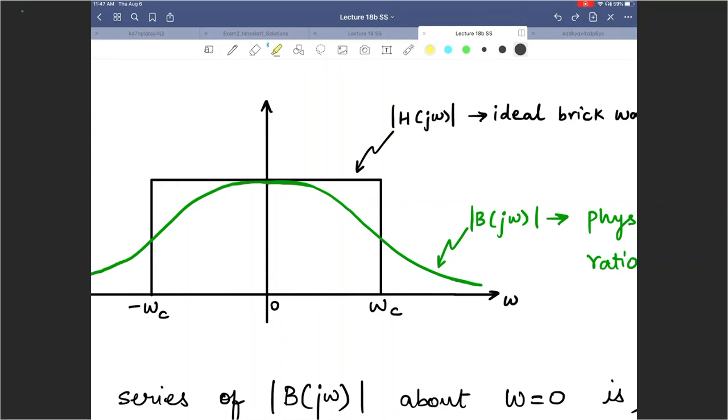Right now I'm discriminating against the higher frequencies here. I don't want that. I want to be fair to all frequencies in the pass band. This is the pass band. So I want to be fair to all those frequencies. But if I go with the green one, I'm not being fair. I will become fair to all frequencies if I had a maximally flat response in the pass band. So that's one.